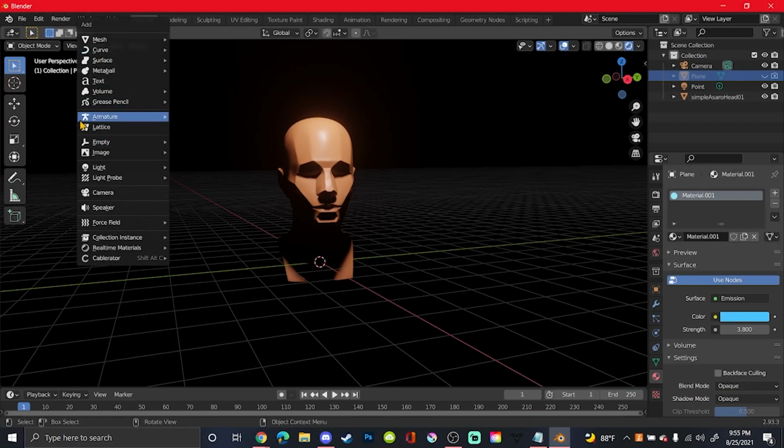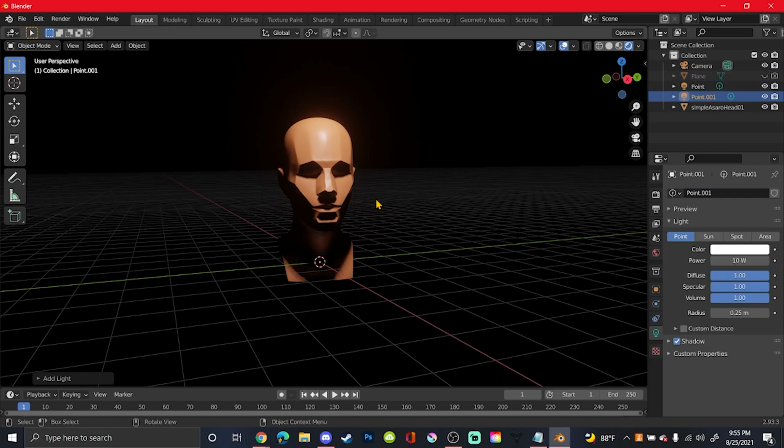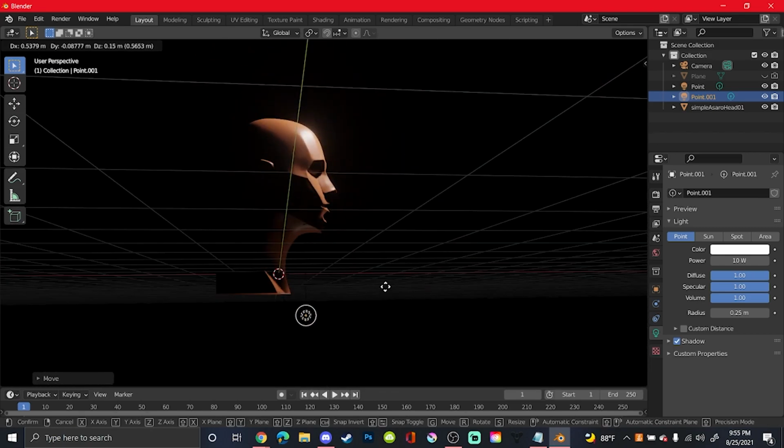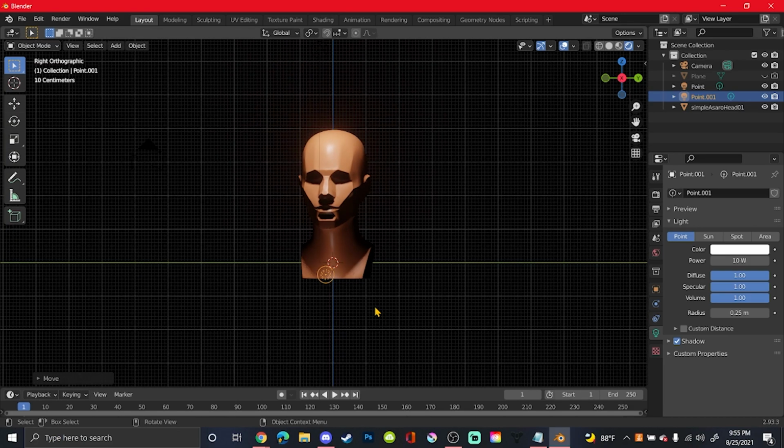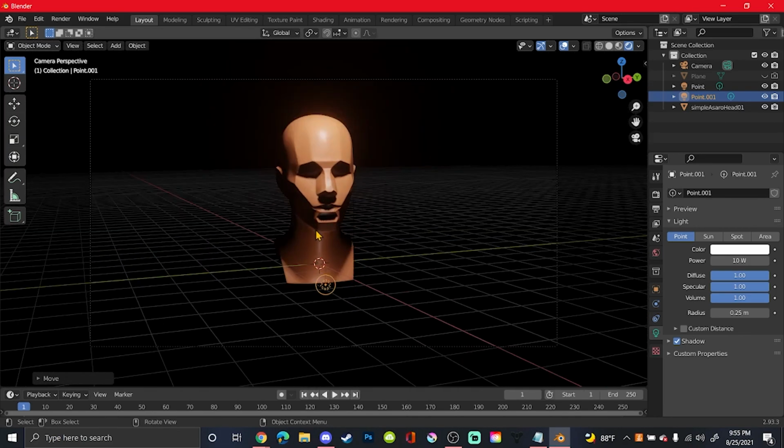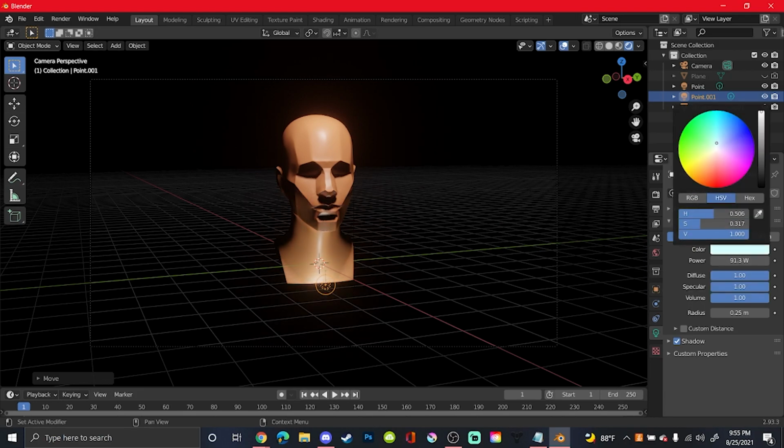So now we're going to add another light source on the point. We're going to just add it below. Add it right there. So 0 on the keypad, and then turn it up, and you can also change the color.